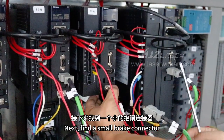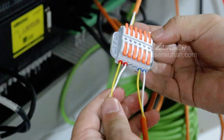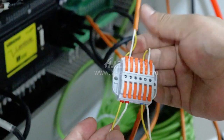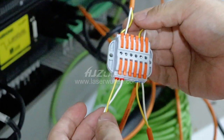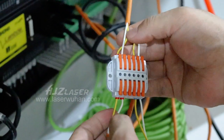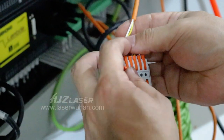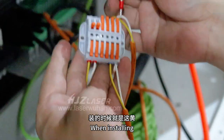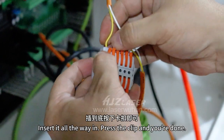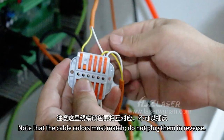Next, find a small break connector. This is red and blue. Do not plug them in reverse. Open the buckle and you can pull out the connector. When installing, connect the yellow wire to the yellow wire. Insert it all the way in, press the clip, and you're done. Note that the cable colors must match. Do not plug them in reverse.